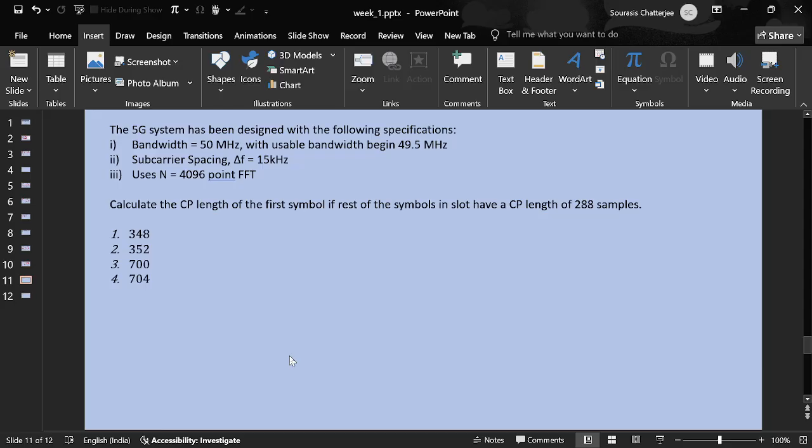But then come the slots, which are subcarrier dependent. Based on your subcarrier spacing, your subframe can contain single to multiple slots, and slots decide the frequency of scheduling the users. And each slot of course contains 14 symbols and 275 PRBs where you can accommodate the users. So that's what I really know until now.